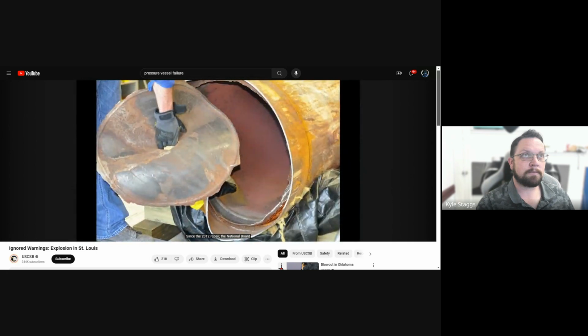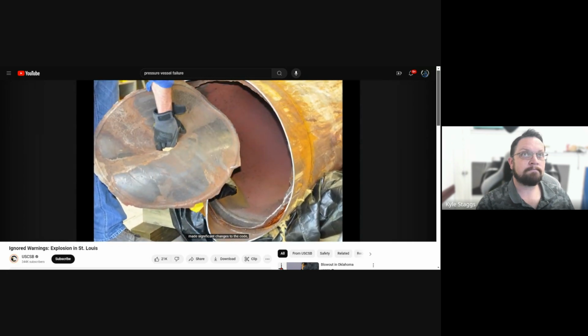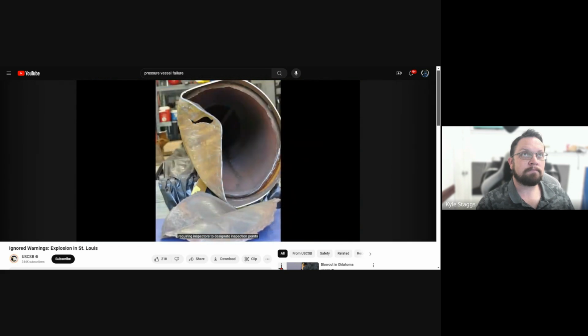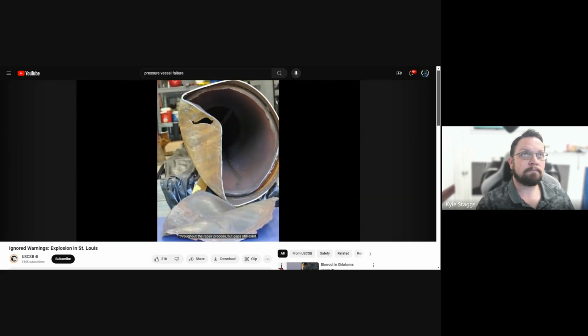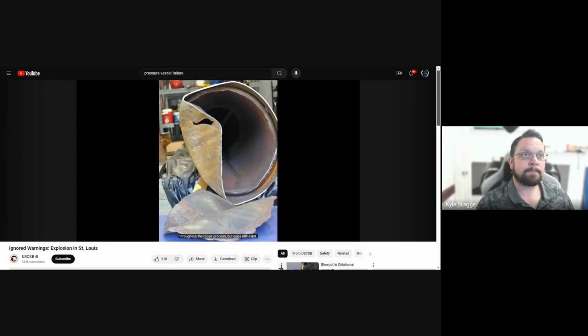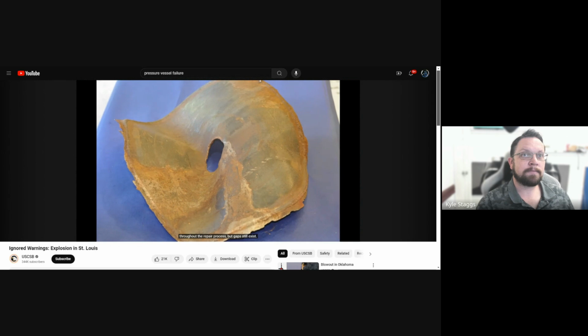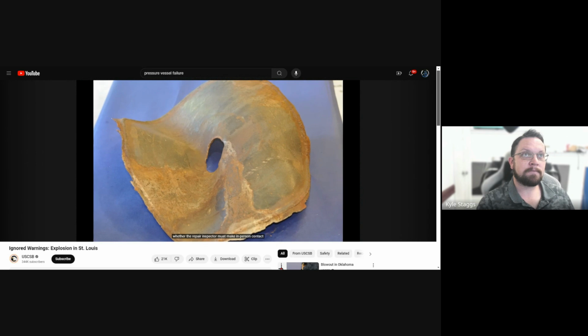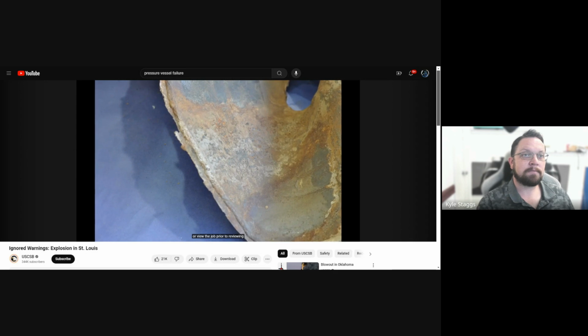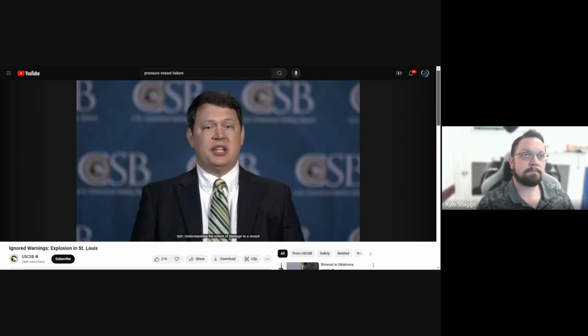Since the 2012 repair, the National Board made significant changes to the code, requiring inspectors to designate inspection points throughout the repair process. But gaps still exist. For example, the code does not specify whether the repair inspector must make in-person contact or view the job prior to reviewing and accepting a repair plan. Understanding the extent of damage to a vessel is a critical step for a repair inspector to make when determining whether a company's repair plan is acceptable.